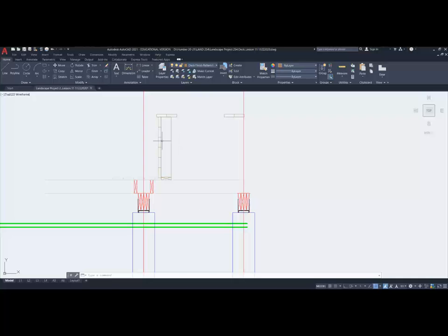This is grade. I'm going to put in a sheet of plywood and probably a 1/2 inch, depending on your application, 1/2, 5/8, maybe 3/4. 3/4 is a bit heavy. Will go down here. Let me show you how that works. So I'm going to put in a piece of plywood, and that plywood is going to be a 1/2 inch thick, and it's going to go down -4 feet. So at 0.5, -4 feet, there's my sheet of plywood.